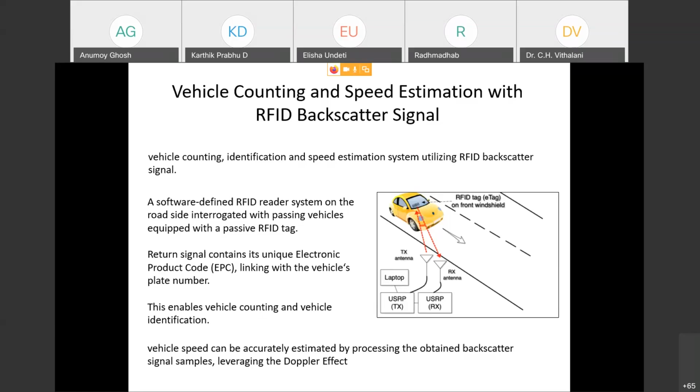Accordingly, the brakes are applied automatically. Now, if the car is moving at 60 km per hour, since the comparator will be sensing a wide difference between the actual speed and the threshold speed, it will be giving out a signal of 15 volts, and accordingly the brakes will be pushed.